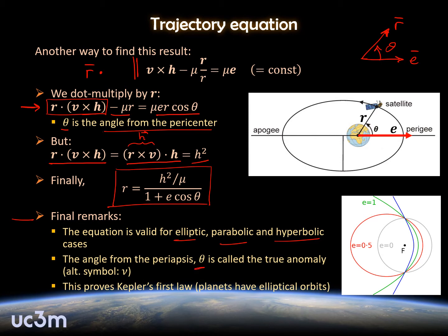The angle theta that we have introduced in this formula is the polar angle, or the cylindrical coordinates angle. It can be called the azimuthal angle, but in orbital dynamics, it's actually called the true anomaly. Okay, and you will see in this lecture and in following lectures that there are many different types of anomalies that we use in orbital dynamics. The word anomaly is a synonym for an angle. So an anomaly is an angular variable, nothing else, nothing more.